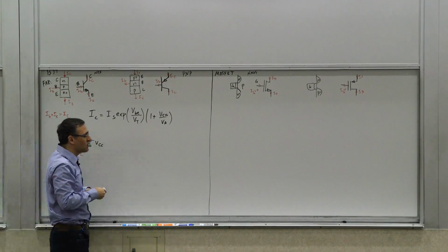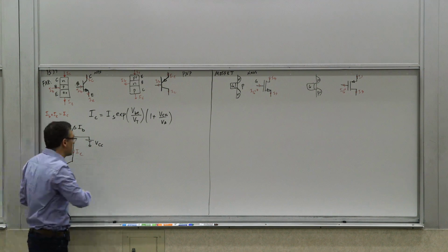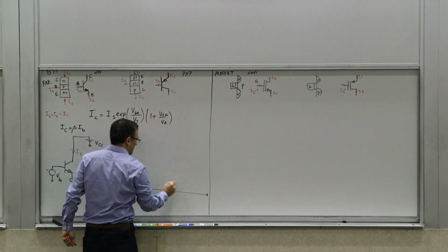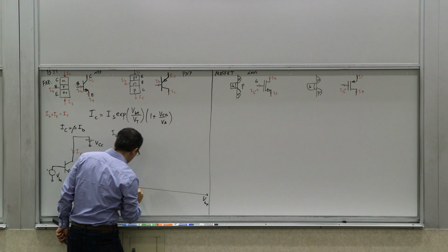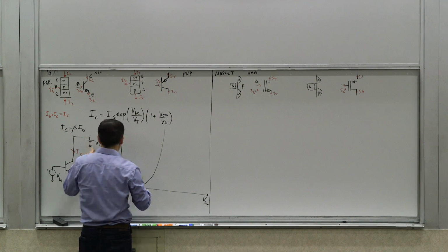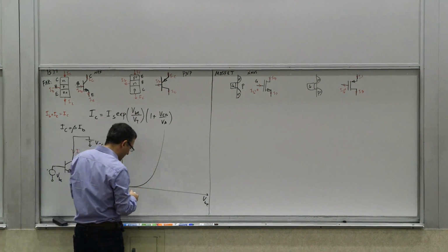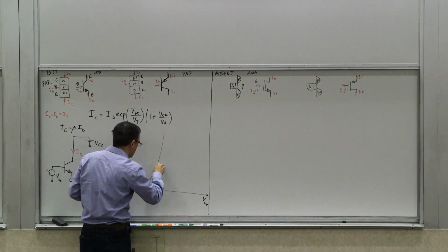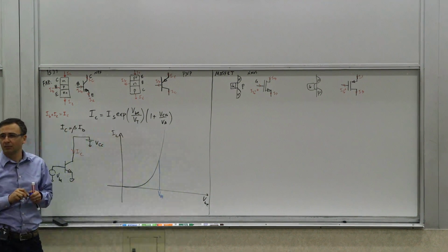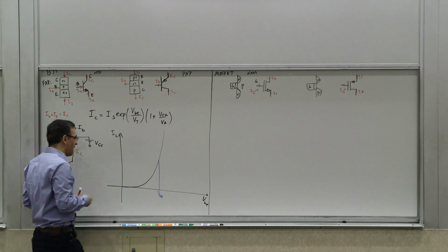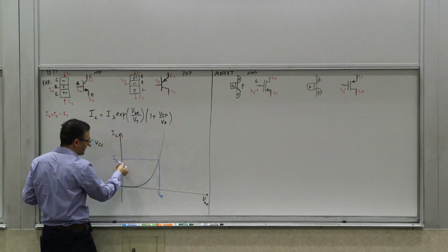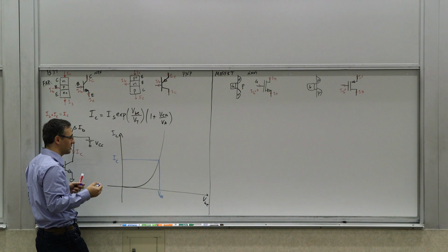So the key question, the most important behavior of this transistor, is coming from what? If you look at this exponential behavior, forget about this part for now, and just focus on the most basic part of it. This is an exponential, right? And as such, if I've set up my VBE to have some DC value, let's call that capital V BE. We sometimes call this the quiescent operating point or the bias point, and that corresponds to some IC. Sometimes you show it like VBQ, ICQ, but anyway, this is the operation point, what we call the bias point, where we have set it up.